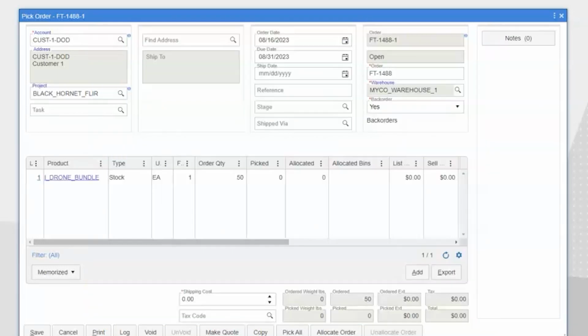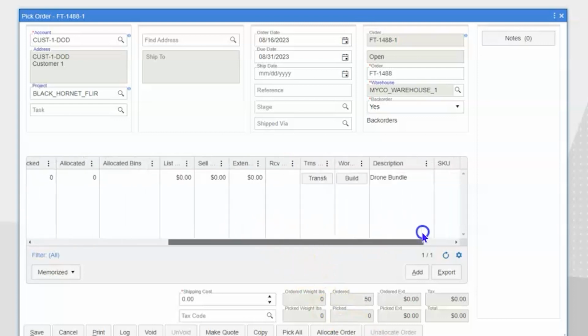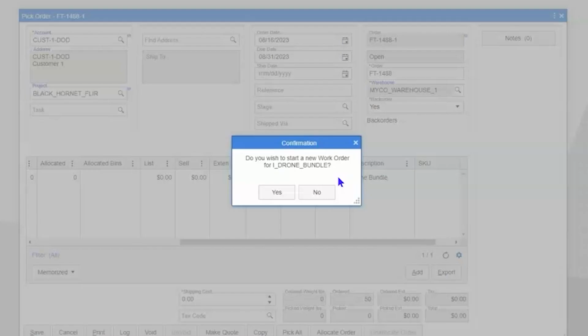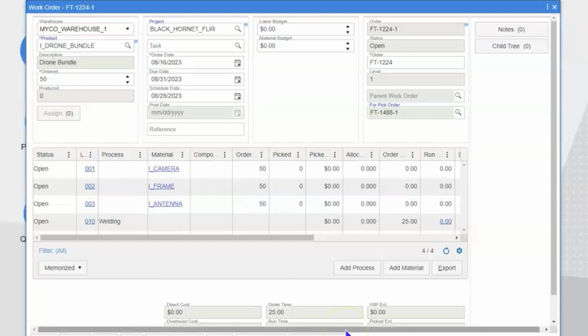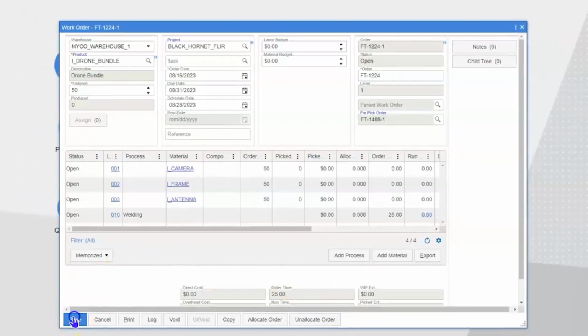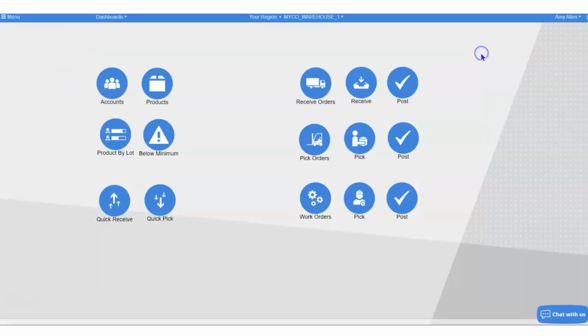I generate a work production order by clicking on the Build icon, seen here. This automatically creates the demand for all the different BOM items, and will also pull on any manufacturing processes that need to be performed. Now let's go see if we need to order any material in support of the work order or production order we just created.